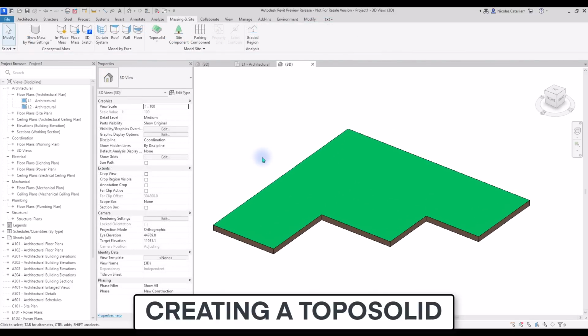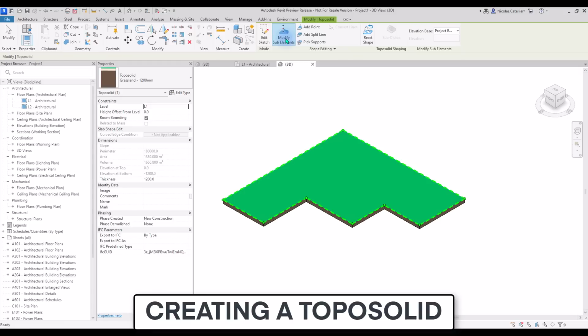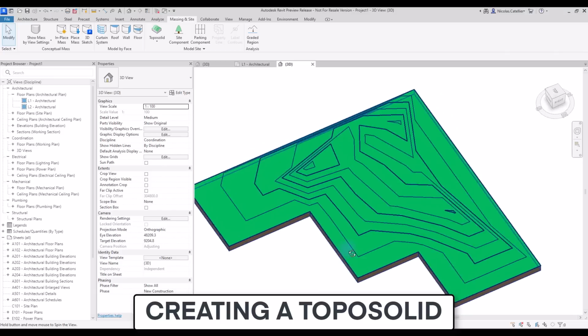Then you can modify the sub-elements in a similar way to roofs and floors. Add points at specific heights to create the topography. Press Escape and you should now see the contour lines.